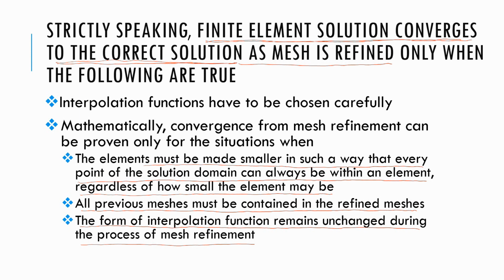In general, for a given problem, we cannot guarantee this. So what do we do? We cannot guarantee that as you refine the mesh, it is approaching the correct solution. So what do we do in practice? For practical problems, we do not seem to worry about this, and instead compare the solution with experiment.